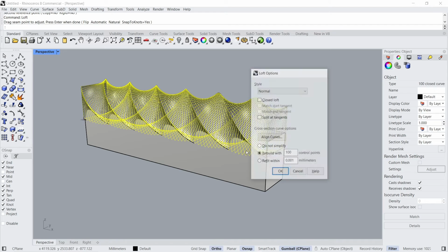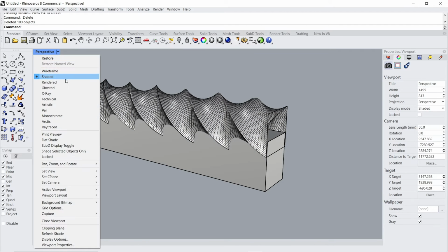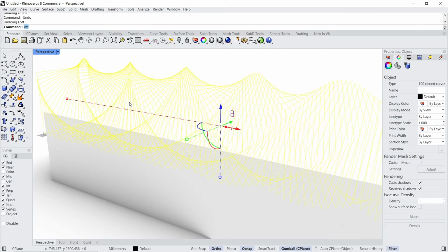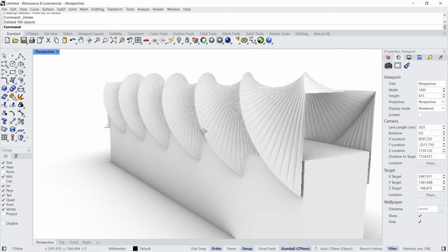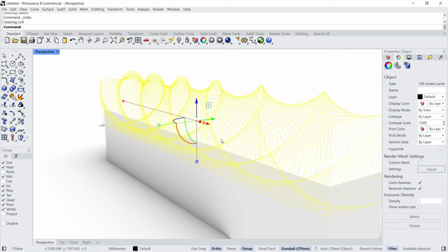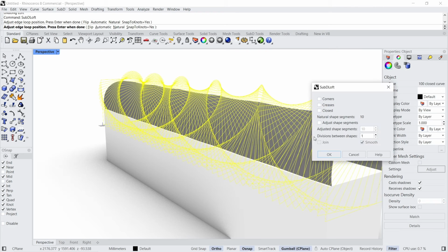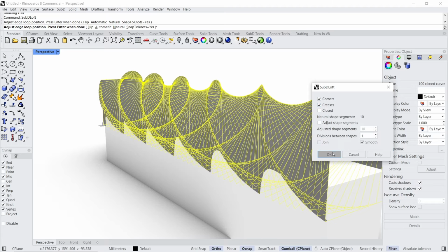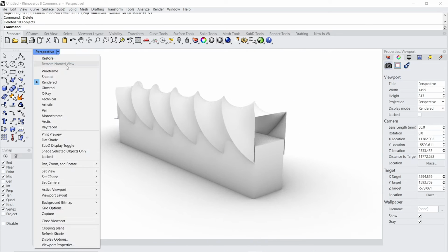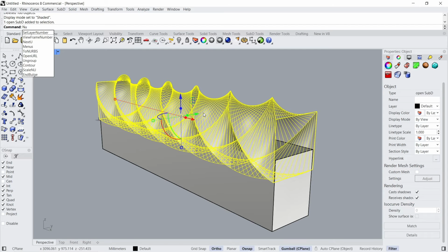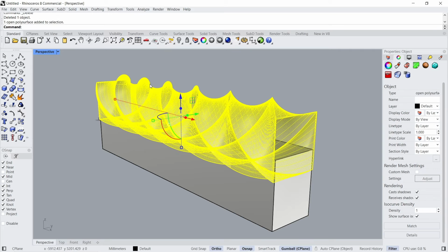Now if I use the loft command, the surface looks weird. So I will use SubD loft and then turn it to a NURBS surface. To NURBS. Delete the SubD, then split the surface with the box.